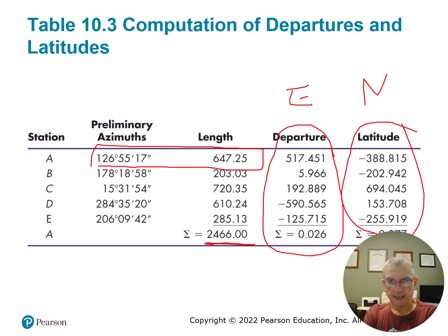So in theory, at that level of precision, in 2,466 feet, we picked up 8 hundredths of error. In order to get a full foot of error, we would have to traverse at this same precision rate 30,342 feet. So that's very precise, adequate for most boundary surveying elements.